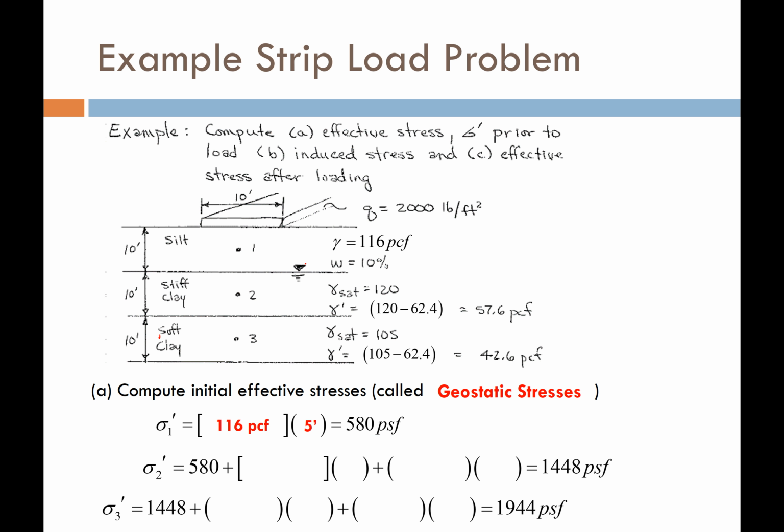Notice, by the way, that the water table is at a depth of 10 feet, which means that below that depth of 10 feet, total stress is going to be different than effective stress. But above the water table, we're going to assume that total stress equals effective stress.